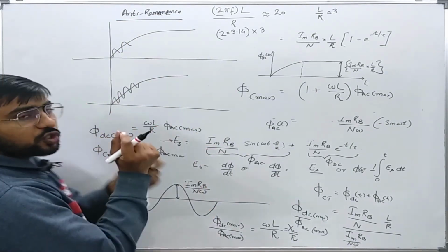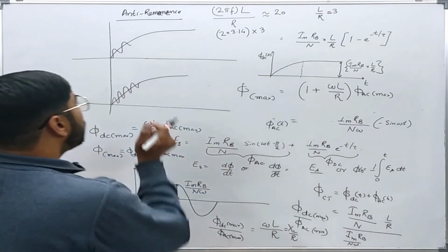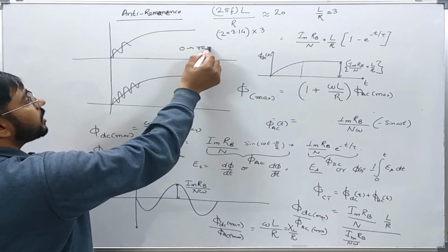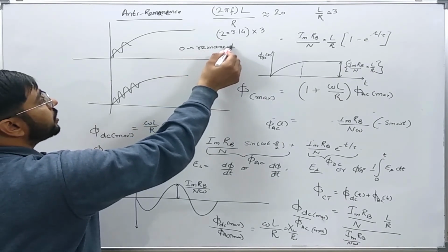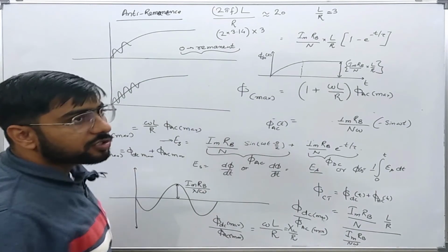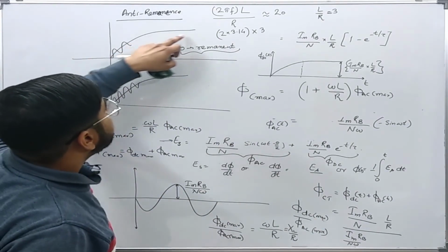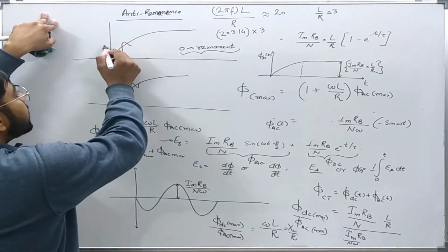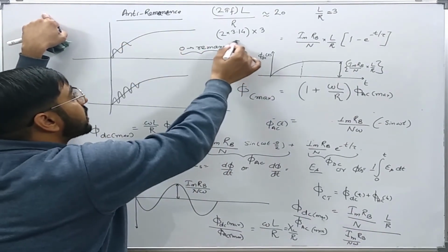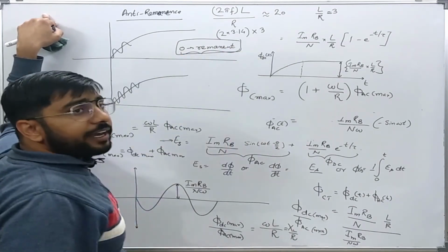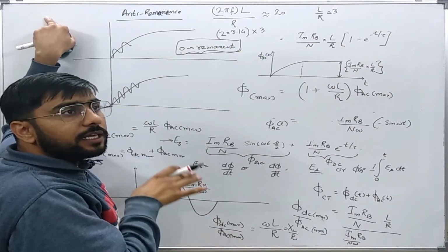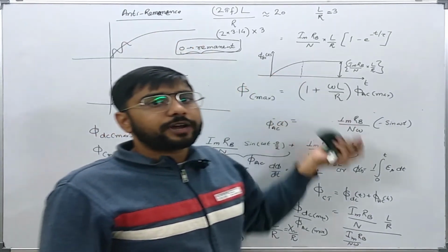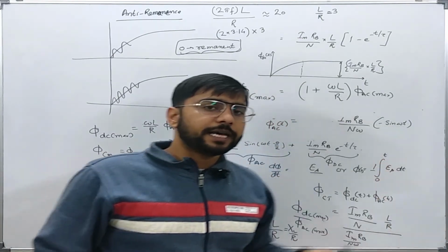It means that those small air gaps will try to ensure there is zero remnant flux available initially, so the DC transient is the only effect, and there will be no effect of the already available remnant flux. Or we may include more air gaps so that the behavior of the core becomes linear. Because of that, the saturation effect will not come into the picture, and linearity will still be there.